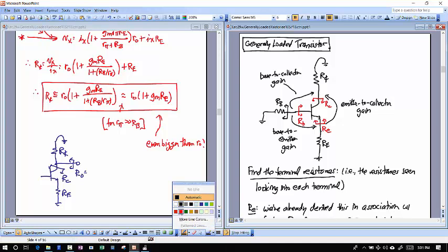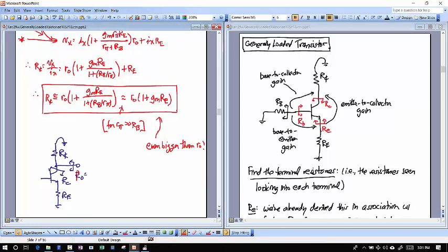Okay, so I just put the line down that RC. But in this case, this R naught is just going to be equal to that RC in parallel with that R capital C. But of course, that R capital C is huge. So this whole thing just boils down to RC. So in this respect, you almost never have to deal with this, that R naught or the R naught times this 1 plus stuff there.